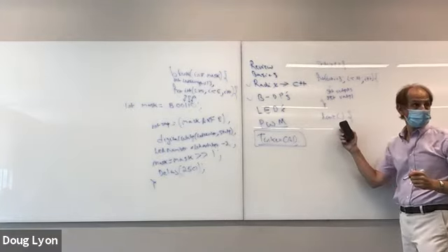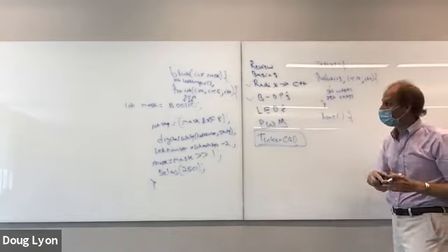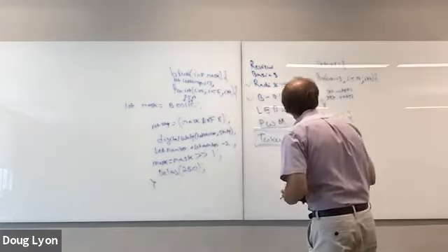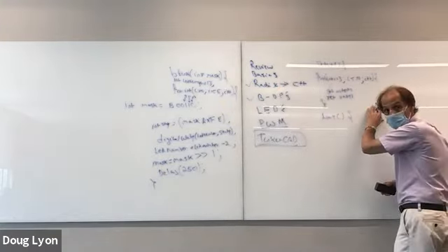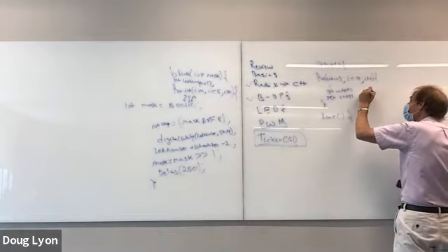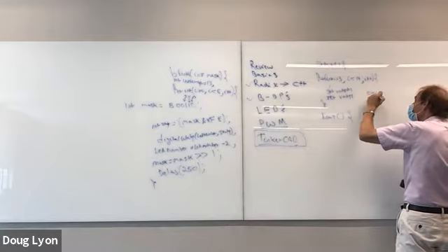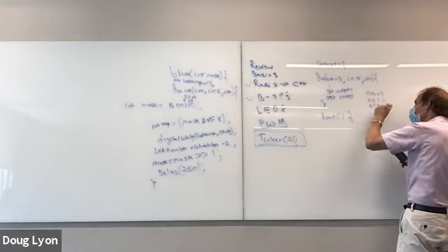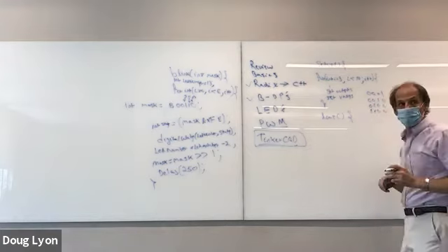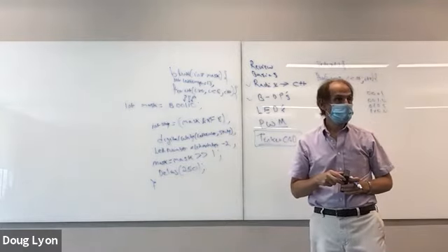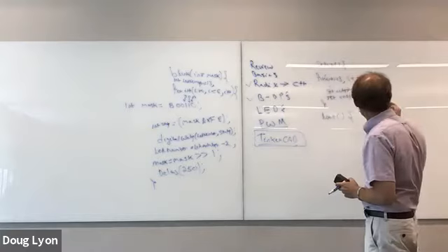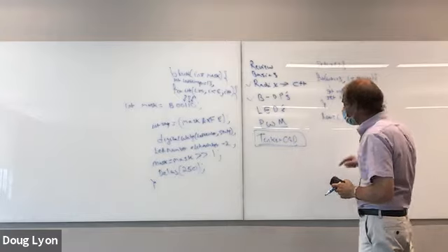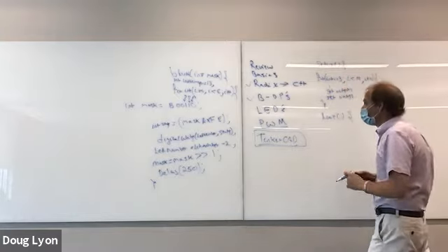And here what you're going to do is you're going to proceed to make use of the blink invocation using a mask. And just to be clear, the mask is going to do something like this. 0, 0, 0, 1, 0, 0, 1, 0, 0, 0. So that's what the mask will do, which means you're going to have to write a for loop that shifts 1, 2, 3, 4, 5. So we'll say a for loop that goes from 0 to 6.